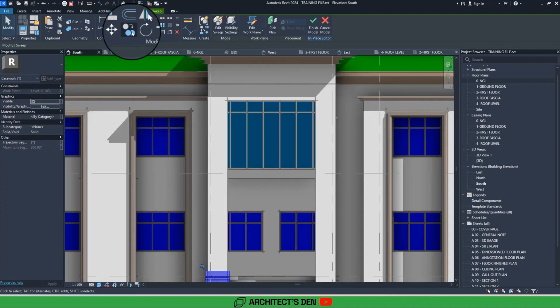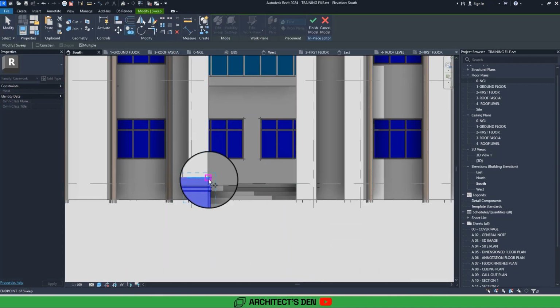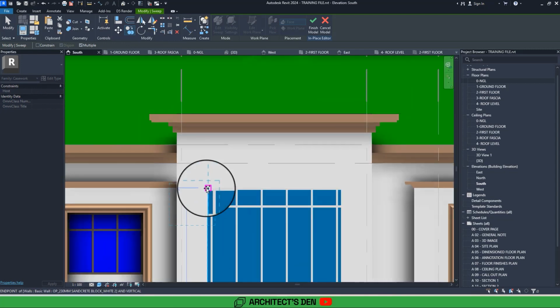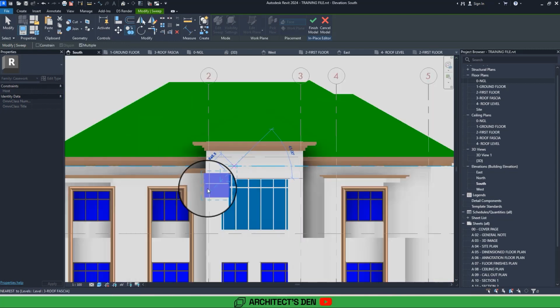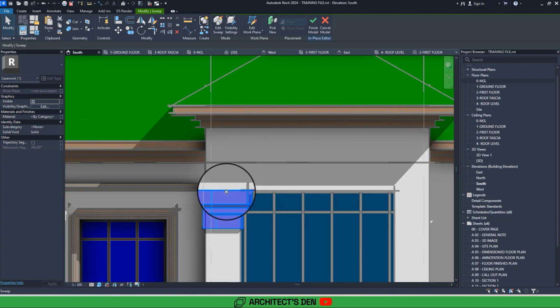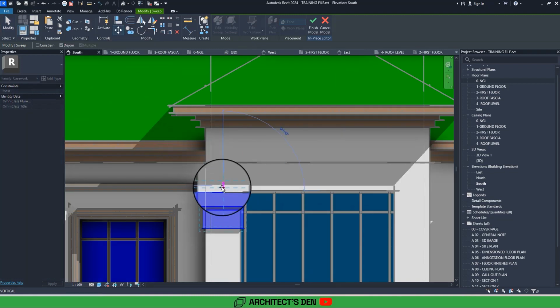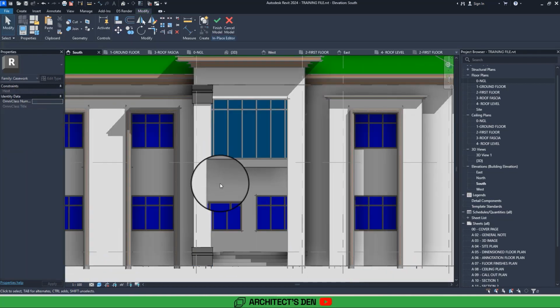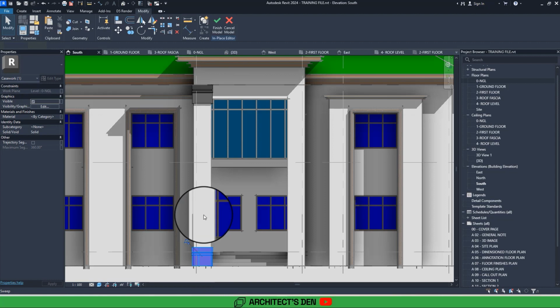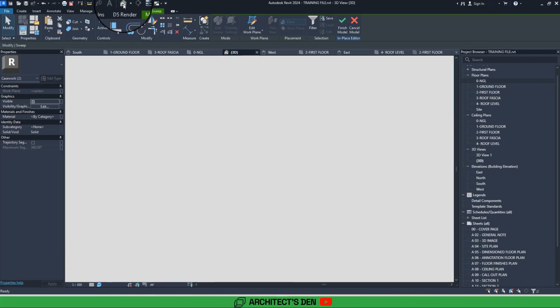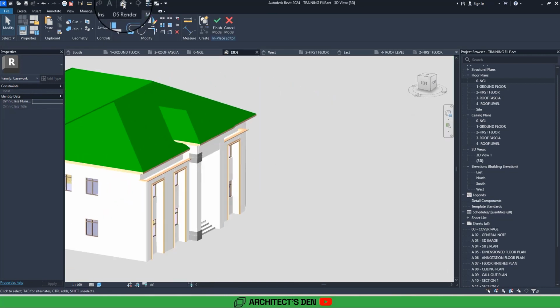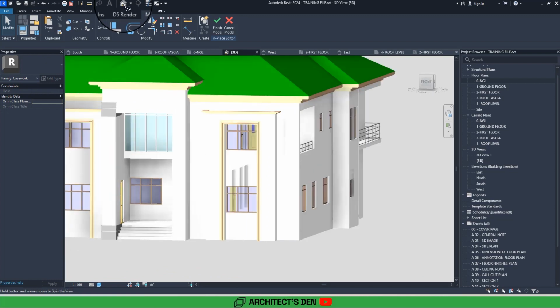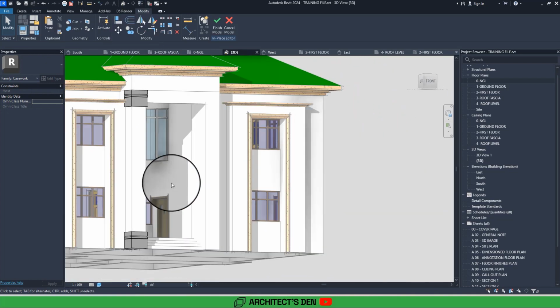And if I copy it up here, to this point. Sometimes I can decide to move it a little bit higher. So what I'm doing is I'm copying and then trying to add moldings, and I'm using solid sweep to add the molding I feel like adding at this point.